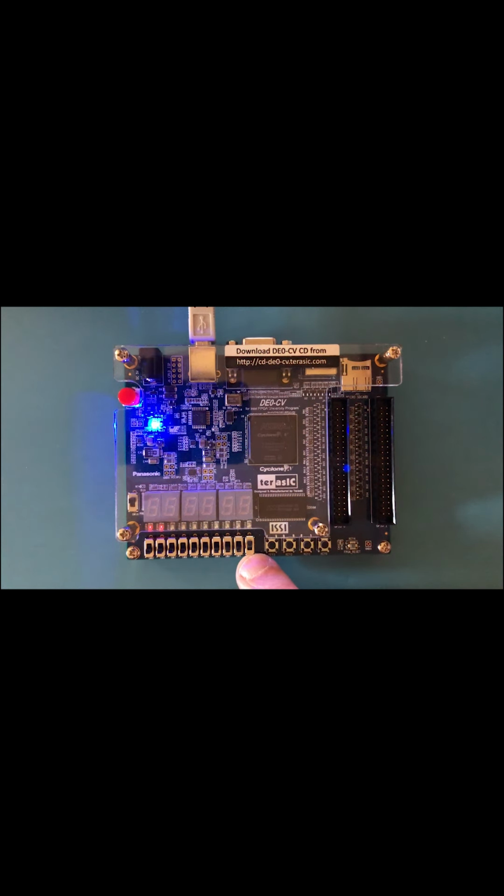Switch 0 resets the program. Switch 1 allows us to go into step mode. And the combination of switches 2, 3, and 4 will change the display, varying from a program counter to opcode, to ALU, the value that's in the ALU, to the name of the student, my name in this case.